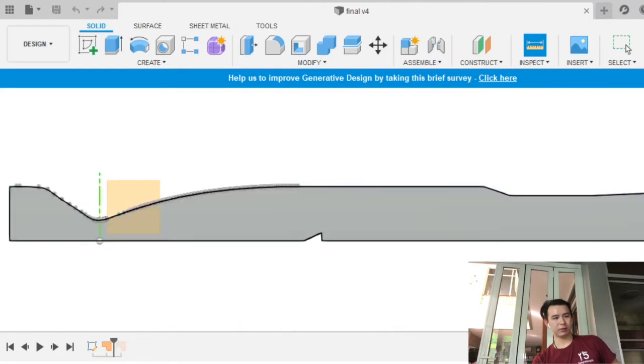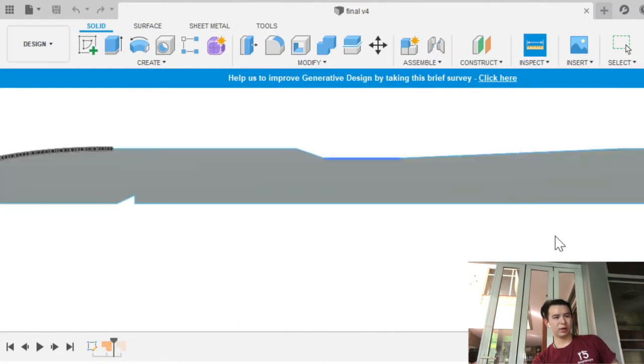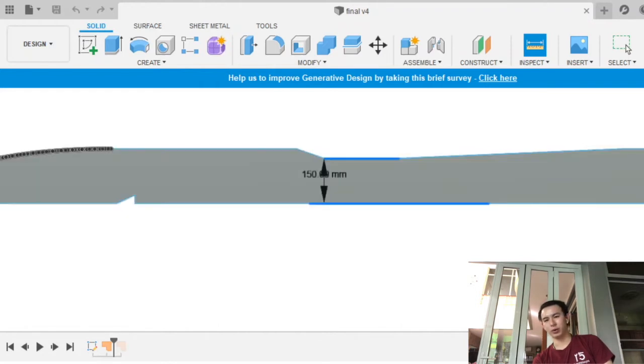And also here the diffuser part, which is 15 centimeters high, which is more than the minimum value of 13.78 centimeters, because the flow did not start the first time we tried this, so I have to increase the height a little bit to make the flow start and reach the wedge here. The flow may start, but it's moving very slowly.